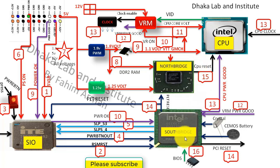Last of all we can see there is the BIOS IC, and the South Bridge or main chip will communicate with the BIOS, and if data communication is successful, then we can see that everything is okay and the display will be shown.